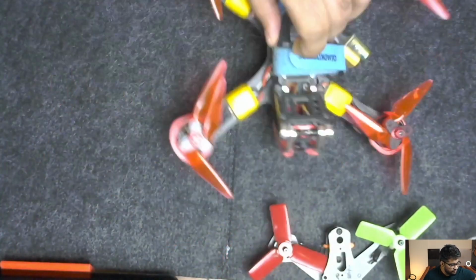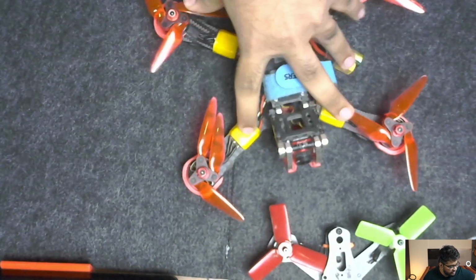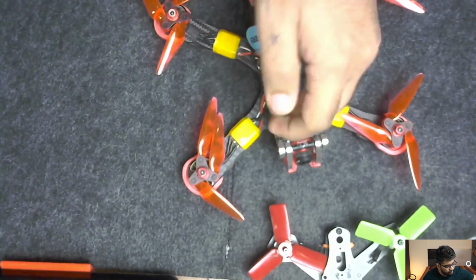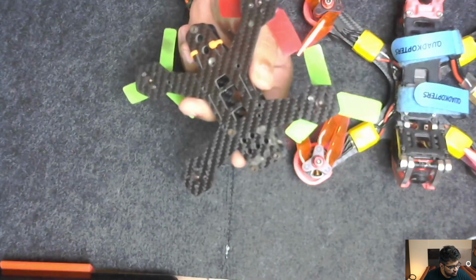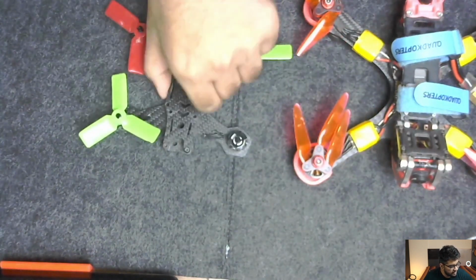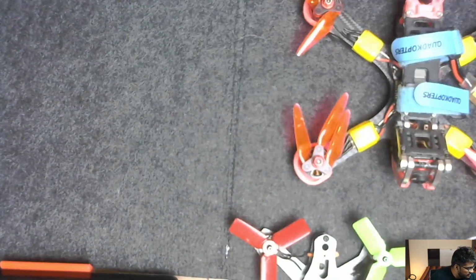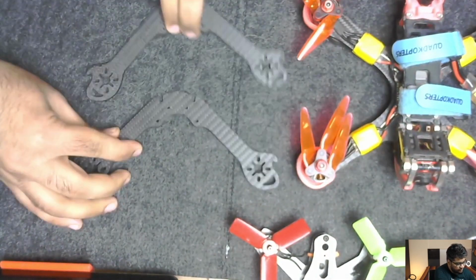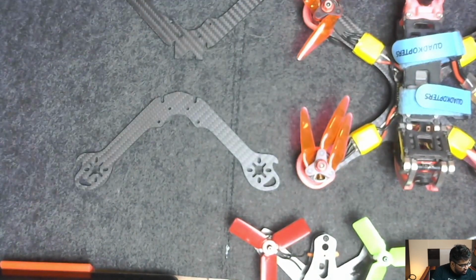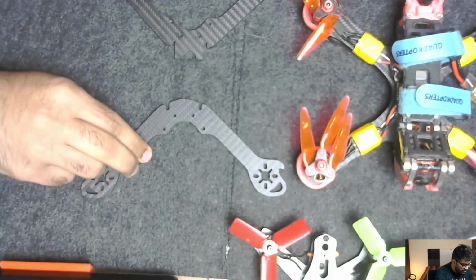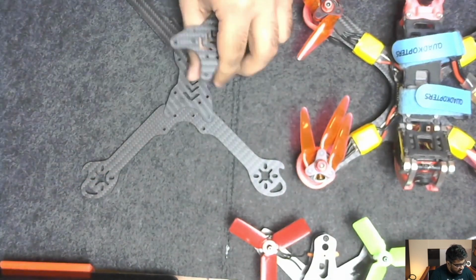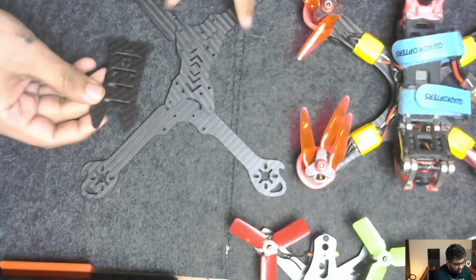So this frame particularly comes with a single bottom plate and a top plate, and this particular part you need to assemble using the screw. This frame is comparatively very easy to assemble. It's just one bottom part and a top part. There are some other unassembled frames I have, which are mostly used for drone racing. So this is one frame designed by my friend. So this has a dual arms like structure. So you'll get two arms in one body. You have a bottom plate, and then you put some standoff, and then you have a top plate.